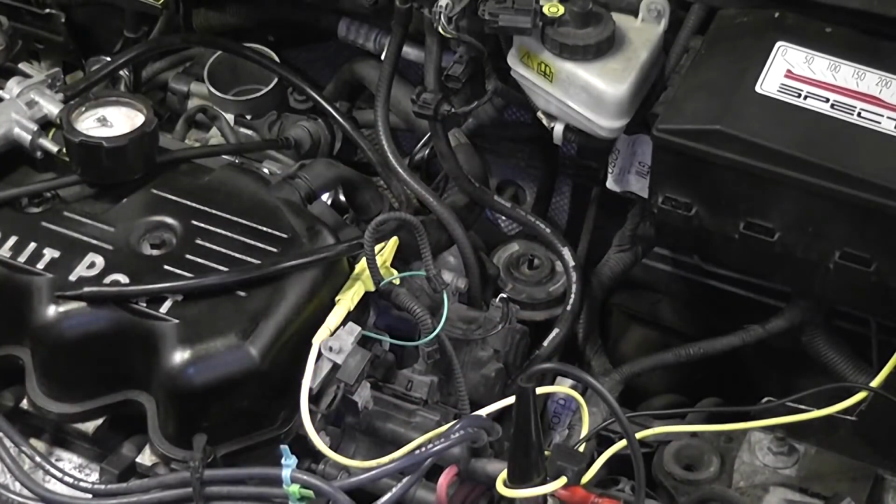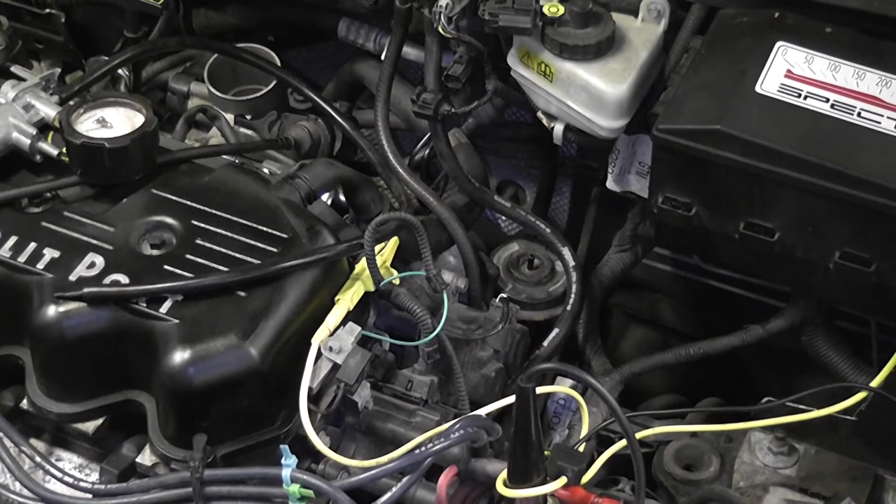So I like the result of that test. That tells me the EGR valve is also good. Tells me the passages are clean, and that when we put an EVR solenoid in this car, we shouldn't have any problems at all with this EGR system. So, Ford EVR solenoid trouble code, open solenoid.